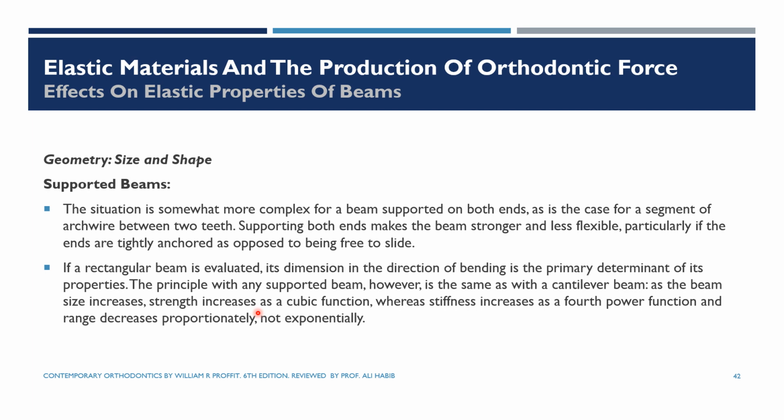But the principle is the same as the cantilever: if the beam size increases, strength increases as a cubic function, stiffness increases as a fourth power function, and range decreases proportionately and not exponentially. A direct, linear relationship.